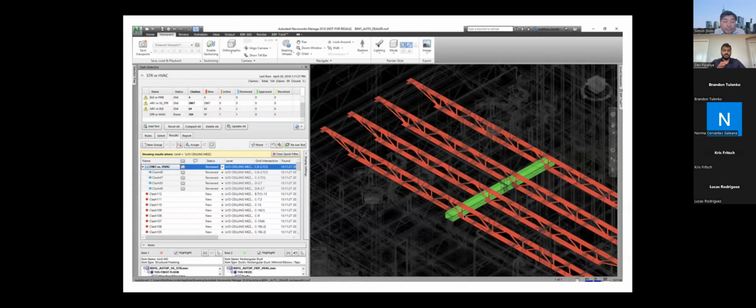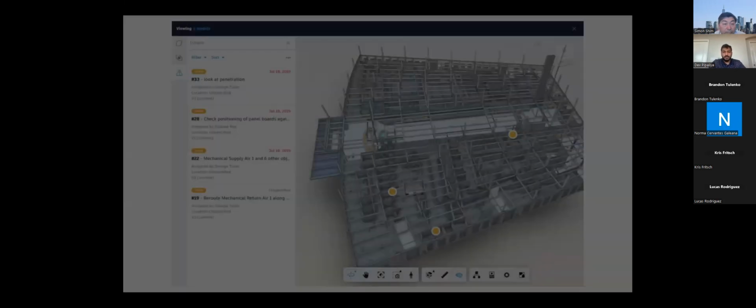So you can just call the duct guy and show him this, and he'll probably have to move the duct out of the structure because you cannot move a structure. I don't know if you can see it clearly, but at the top there's an issue count that says 2600 issues. This is all pre-building. The building has probably not even started yet, and they already have this many issues. That's why you really need a BIM model. Before a building is actually started, you can find out all the possible issues that are going to be there and try to deal with them already.